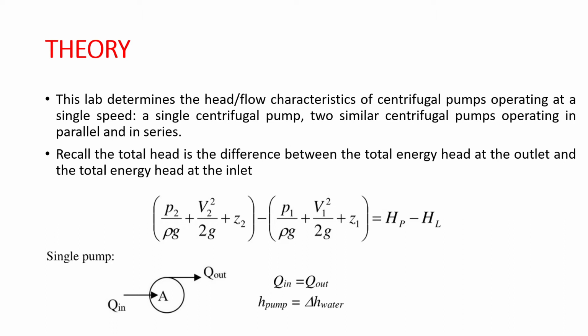at the inlet, neglecting the small differences in velocity heads, as shown in the following equation, or in other words, the Bernoulli equation. In this equation, subscripts 1 and 2 refer to inlet and outlet sections. A_P is the pressure head produced by the pump, and A_L is the energy loss due to friction and pipe fittings. By conservation of mass, V_1 equals V_2 if the pipe diameters are equal at the inlet and outlet sections.